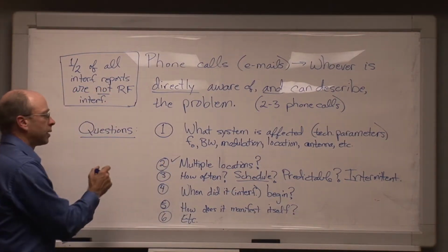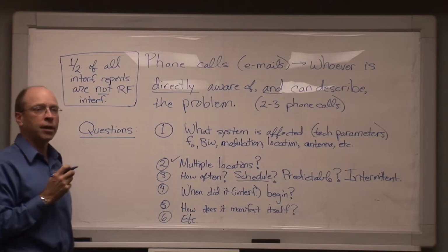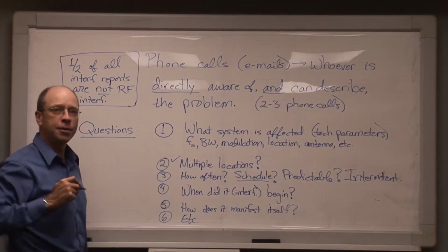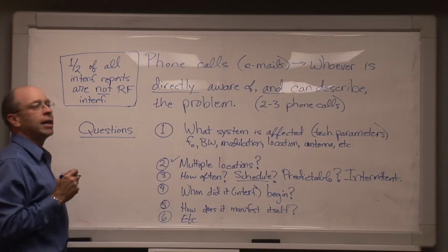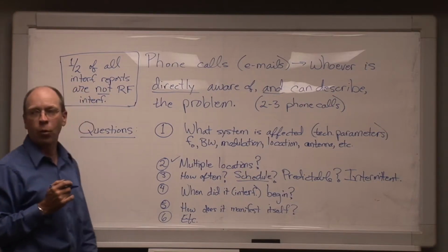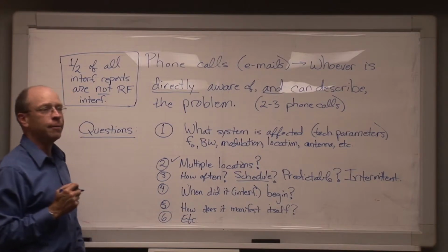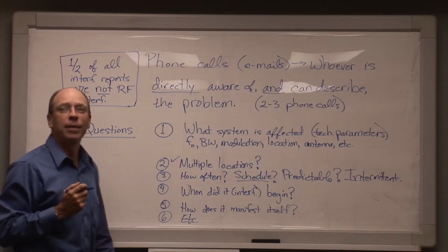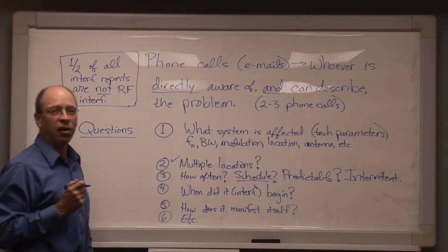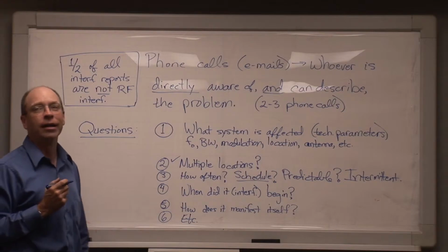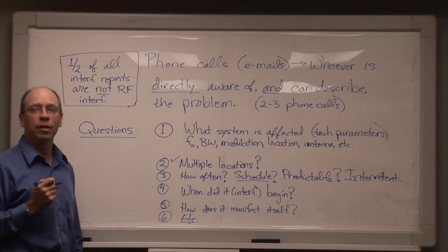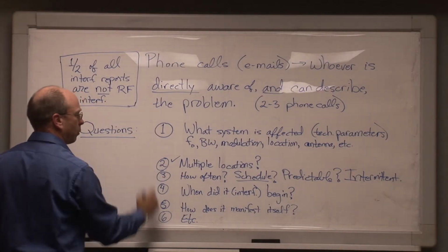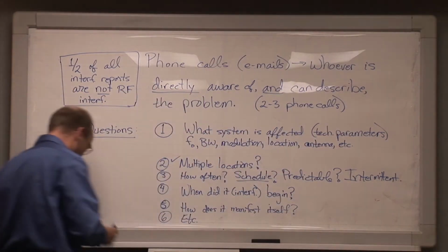For example, we've had interference to Earth station links, bringing signals down from satellites, which were occurring entirely in coastal locations in the continental United States, Hawaii, and Japan, but never occurred more than a few miles away from the coast. What might that mean? Maybe it's coming from ships offshore, because for some reason it occurs in California, Hawaii, and Japan, but it doesn't occur in Nebraska. So now you can start thinking about what might be offshore and what might be going on there.